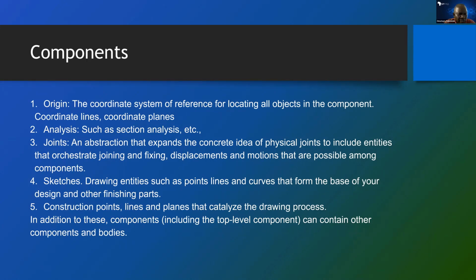Number 4, inside your components, you can have sketches, which we will say much more about shortly. A sketch is a combination of drawing entities such as points, lines, and curves that form the base of your design and other finishing parts. So you can have several sketches in a single component. If you have several sketches, they will be in the sketches section, and there can be more than one sketch there.